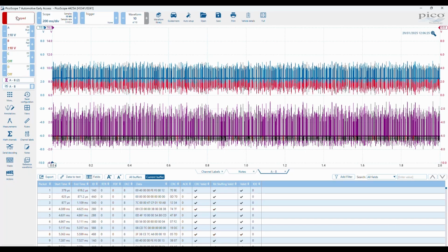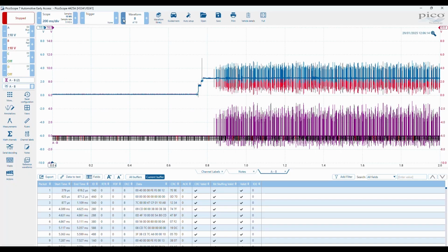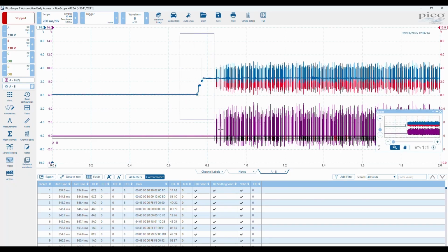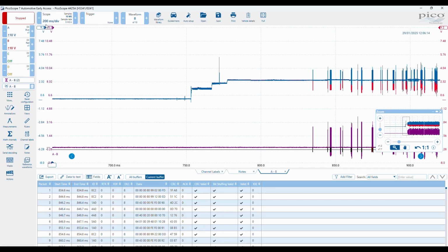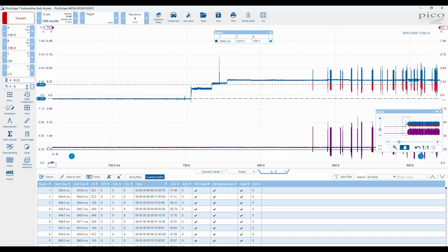Let's go back to the wake up, because there is diagnostic information in the wake up. There it is, various stages as well. We go from our rest or sleep, I think it was around about 880 millivolts. Here we come up, first stage was 1.46.